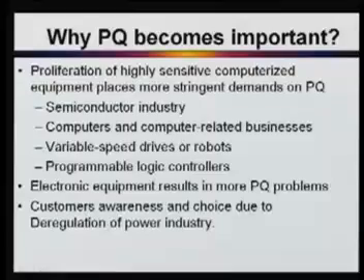For a voltage swell, if the voltage is more than your normal 1 per unit, say 1.1 to 1.8 per unit for a duration of less than 1 minute, it may damage the insulation, because high voltage may cause insulation damage, and therefore it is a permanent fault. We have to replace the insulator, and that equipment must be replaced.